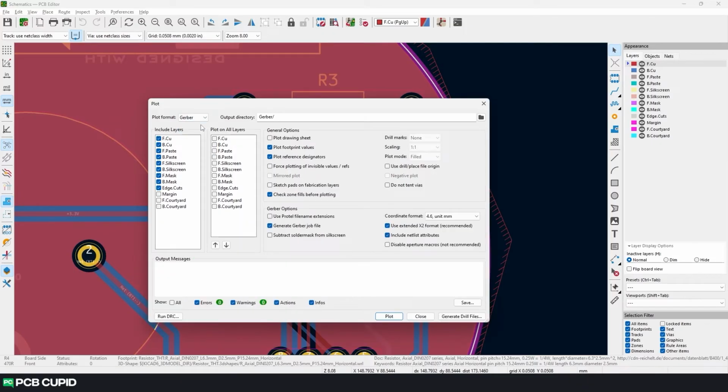We don't have to use this option as well because it's on the fabrication layer which we disabled previously, but make sure to keep the next option checked, because KiCad will perform zone filling again before generating the Gerber file. So if we have messed up something while performing DRC, that can be fixed here.